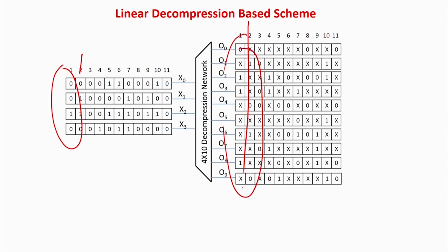So I can easily solve some Karnaugh map optimization and I can have a general digital circuit for that, a combinational circuit. But that I don't want to do. I only want to do it by linear operations, so that this decompression circuit is small. So only by XOR gates, such a structure. So is it possible? The theory says that we have only 4 ones here. So let me just try to keep this number as 4.